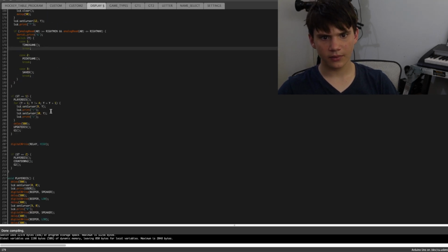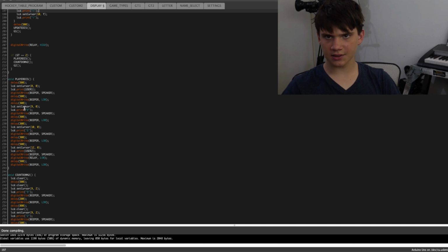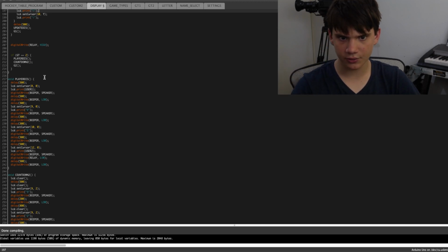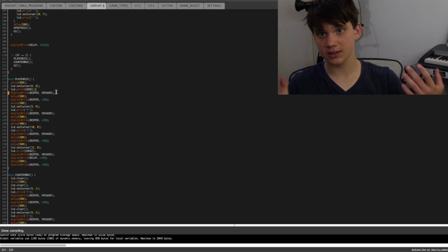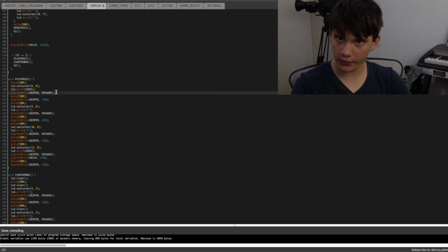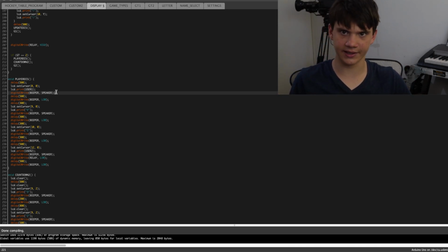If GT equals 1, player dis, which is player display, and that's actually going. As we can see, this is where we can change which player name you are by using strings user1, user2. So it goes ahead, delay 500, LCD.setCursor 0,0, which is the top left corner. And then LCD.print user1, speaker, beeper, speaker. Now again, speaker is that boolean, and you can change the boolean. If boolean is 1, the speaker will be written to 1. If it is 0, the speaker will be 0 and not make a sound. That is how we can turn the speaker on and off.